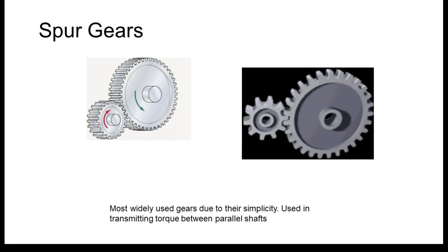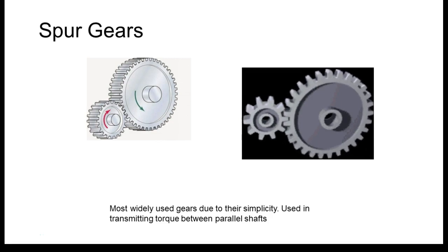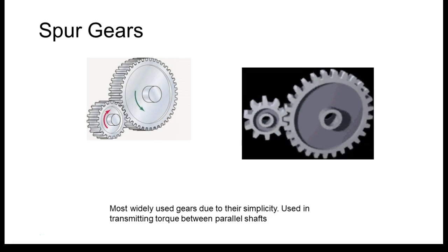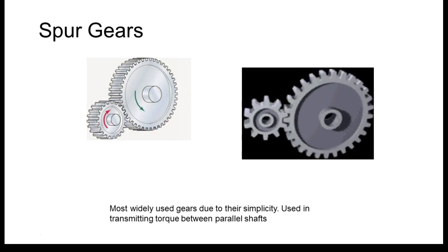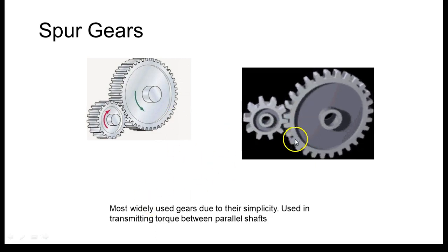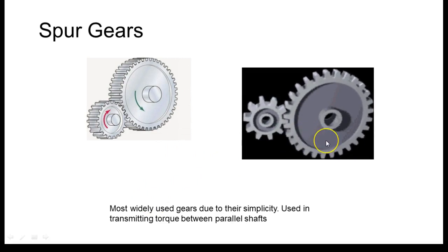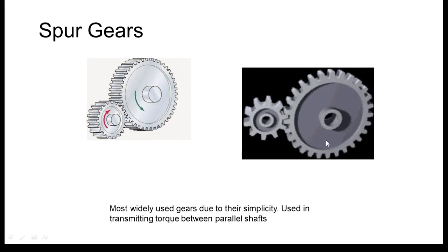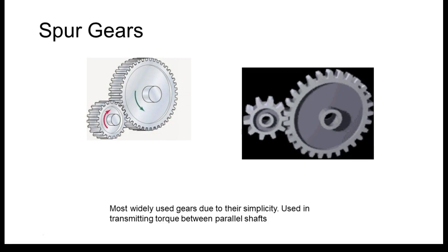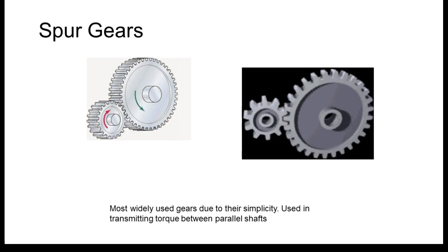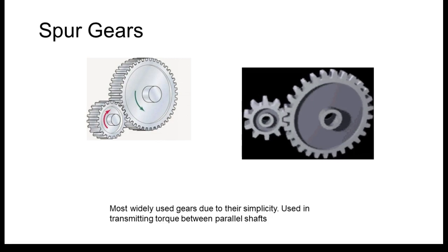The problem with these is they're pretty noisy. It's because of the face of the tooth, which engages with the face of the other tooth. The bigger the faces are, the more torque we can generate between the gear sets, right? That makes sense. These guys are real noisy.